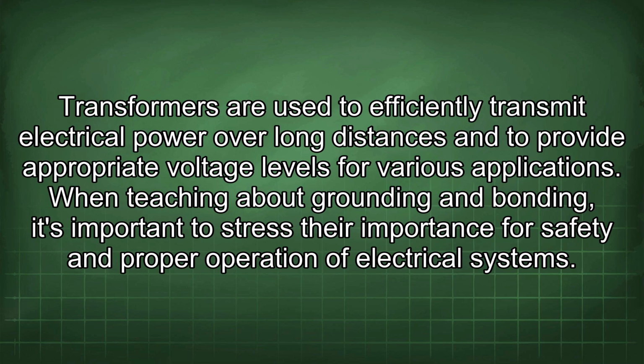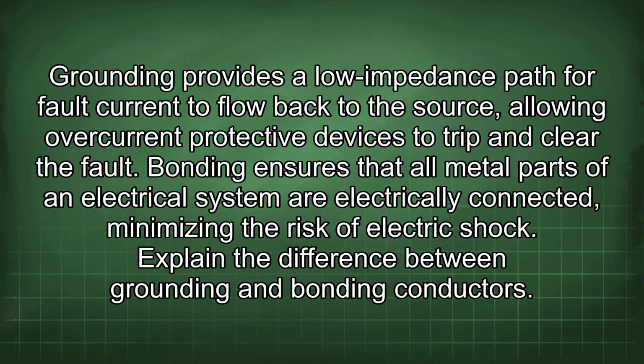When teaching about grounding and bonding, it's important to stress their importance for safety and proper operation of electrical systems. Grounding provides a low impedance path for fault current to flow back to the source, allowing overcurrent protective devices to trip and clear the fault.